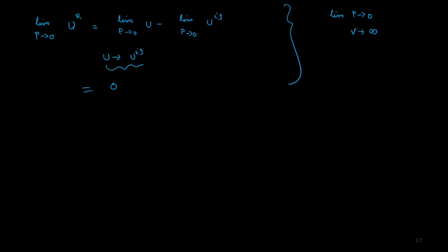The temperature is same, so other types of molecular level energies are going to be same for ideal gas as well as for a real gas. Only thing, as you approach the zero pressure limit, in the real gas, the intermolecular forces go to 0, and then the total internal energy will be same as that of an ideal gas, and so the residual internal energy is going to go to 0 as we approach the zero pressure limit.